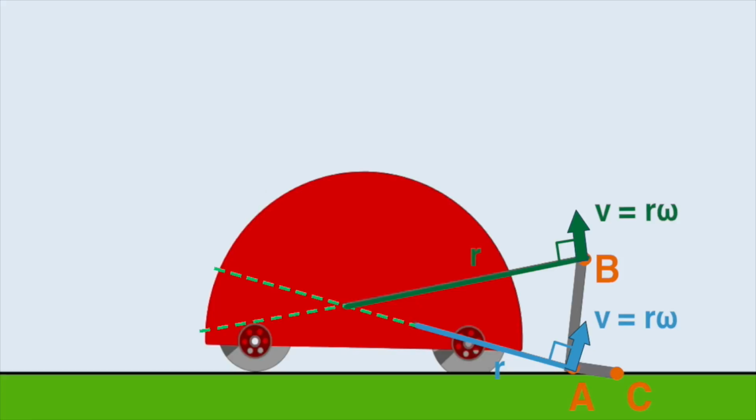Now, the important thing to realize here is that at A, the velocity of the link is the same for both the coupler and the link that connects back to the robot, because they're connected by a pin, right? That pin has the same velocity where it's touching the link that goes back to the robot and where it's touching the coupler itself. Okay, so if we extend that radial line out that passes through A, and then also extend out the radial line that passes through B, they will intersect at the instantaneous center for the coupler. And those velocities, as we just said, will be the same.